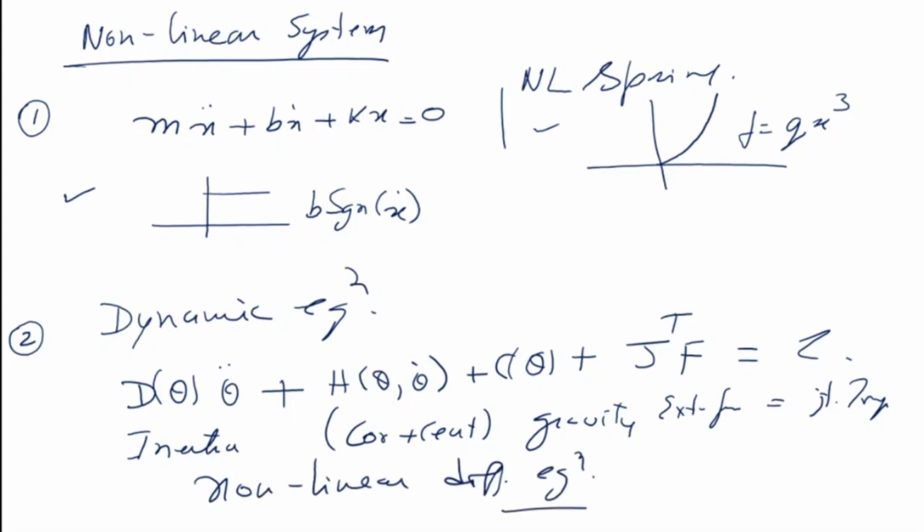So it basically means that a robot manipulator's equation of motion is a nonlinear differential equation. Although we talked about linearizing, we can linearize the system at a point, but a robot manipulator is going to operate at different points. So trying to linearize it about one point in the workspace really doesn't help. The other way is to use the partition control system.